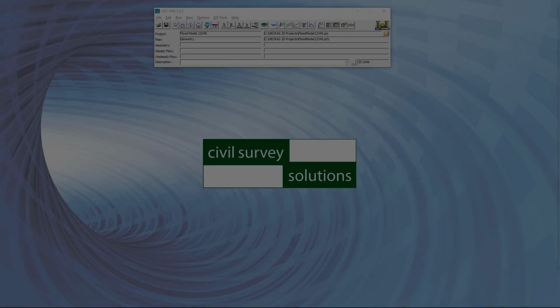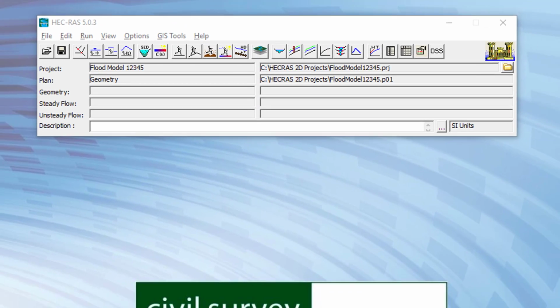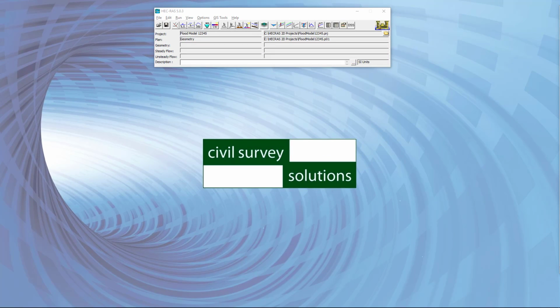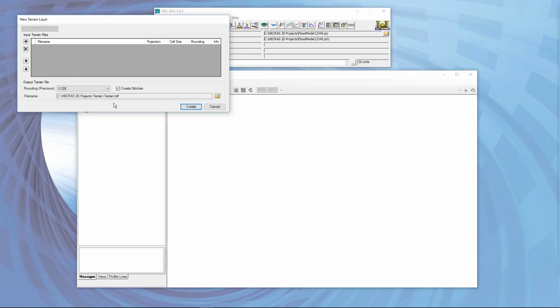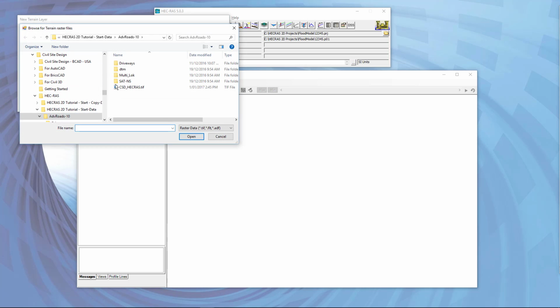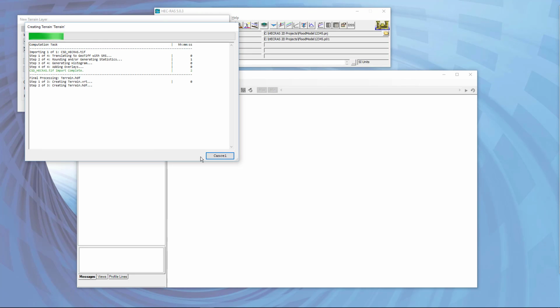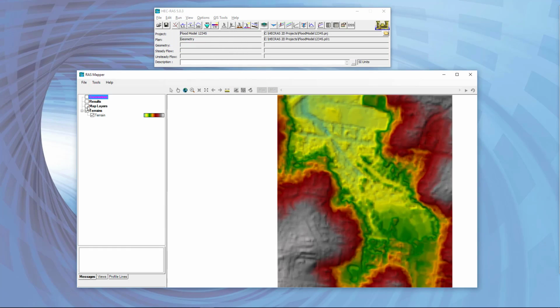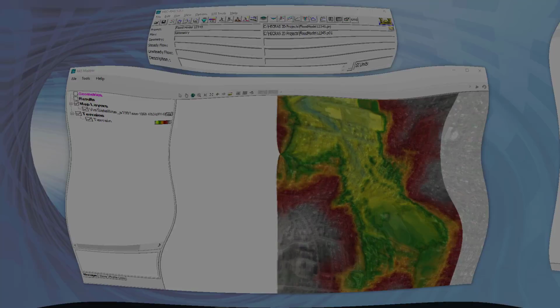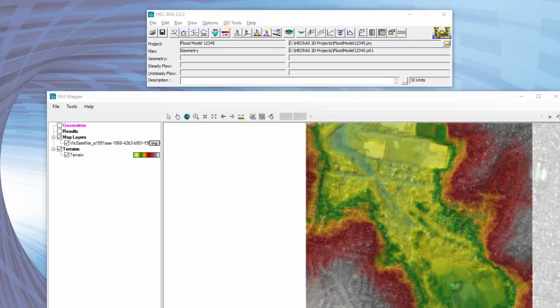We will quickly step through the fundamental processes involved in analysing flows in HEC-RAS. In HEC-RAS, RASmapper is used to add terrain data into HEC-RAS for 2D flow analysis. It is here that the exported GeoTIFF file generated by Civil Site Design can be used to create the terrain. Additionally, the image you created can also be added as a map layer to use as a reference for establishing boundary and other controls. There are three key aspects to analysis in HEC-RAS.